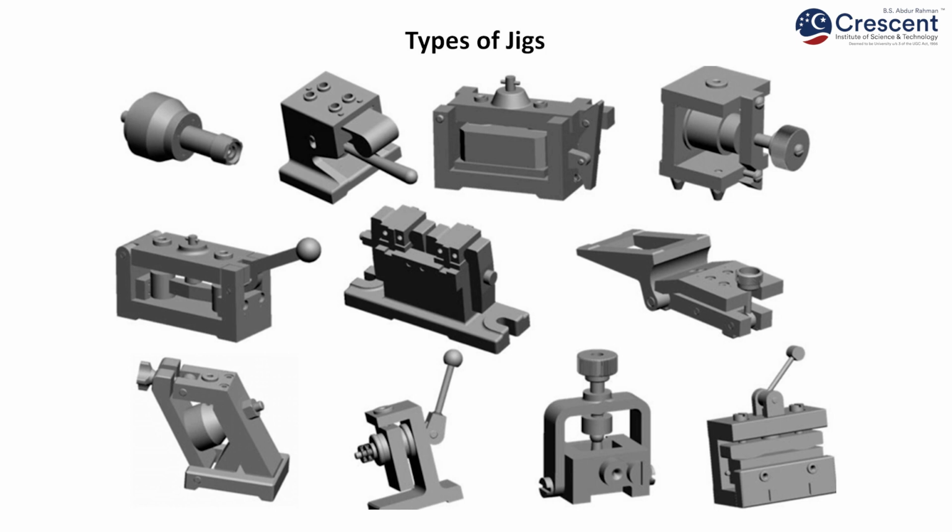Assembly jigs, as the name suggests, help in the assembly of complex products, positioning and securing the components in the correct orientation. Inspection jigs, of course, we also have the inspection fixture. We also have the inspection jig. It is used for quality control and inspection to verify that the workpieces or components meet the specified dimensions and close dimensional tolerances. We have the routing jigs, which guide routers in woodworking or other applications to cut shapes, patterns or designs in materials. We also have the grinding jigs, which guide grinding wheels or abrasive tools for precision grinding operations.